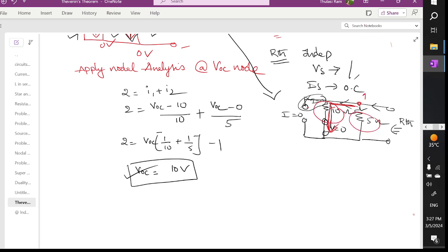So let's mark it if you are having any confusion. 1 and 2, how many resistors are there? 2 resistors. The current starts flowing like this, and the current is going to divide. When the current is dividing, you can say that these two are connected in parallel connection.